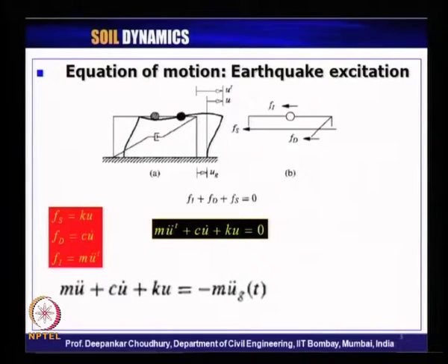The major points were we had discussed the formulation of the equation of motion when there is earthquake excitation, and we had identified that it is a forced vibration case with earthquake ground acceleration u_g double dot t at ground level.